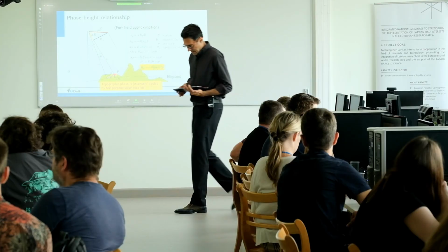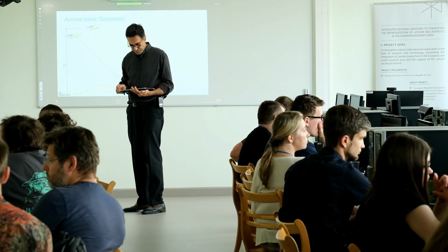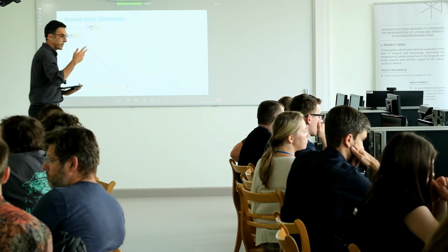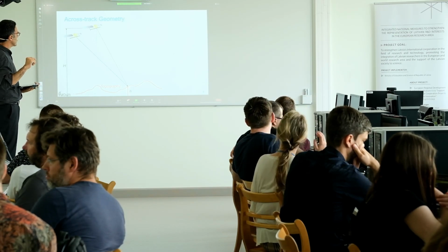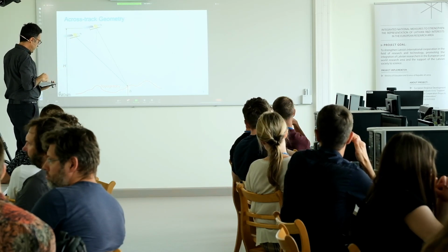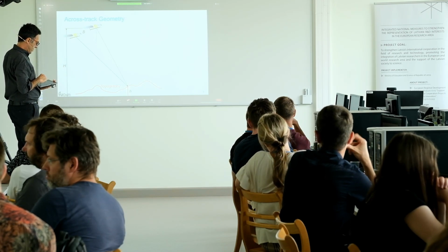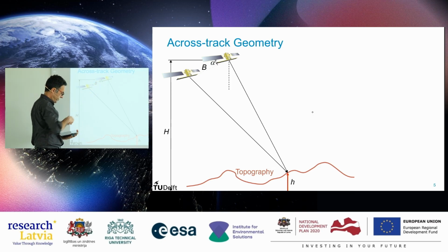Okay, so I have this also in a different explanation with a little bit different figures, just to get it across. Again, the same situation, 2 satellites, topography over here, and what we do now is we put the baseline over here. This orientation of the baseline we get from the satellite positions. We have the perpendicular baseline, the distance, and the delta R that I was indicating.